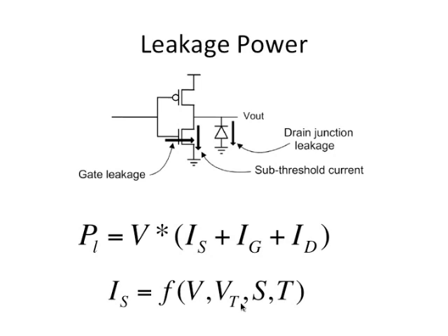the threshold voltage of the transistor Vt, and S, the size. Yeah, this is a confusing notation. S is also used for subthreshold slope, but in this particular slide I am using S to represent the size of the gate. The bigger the size, the bigger the current. It also depends on the temperature.